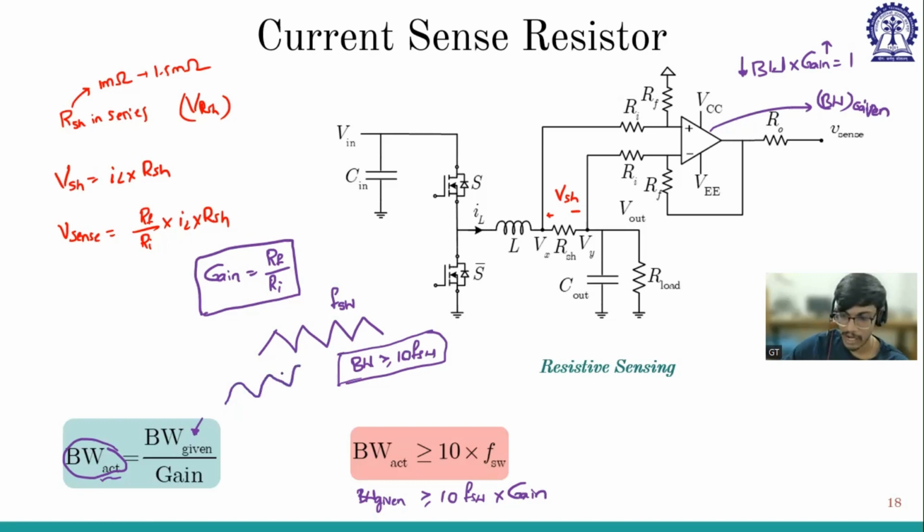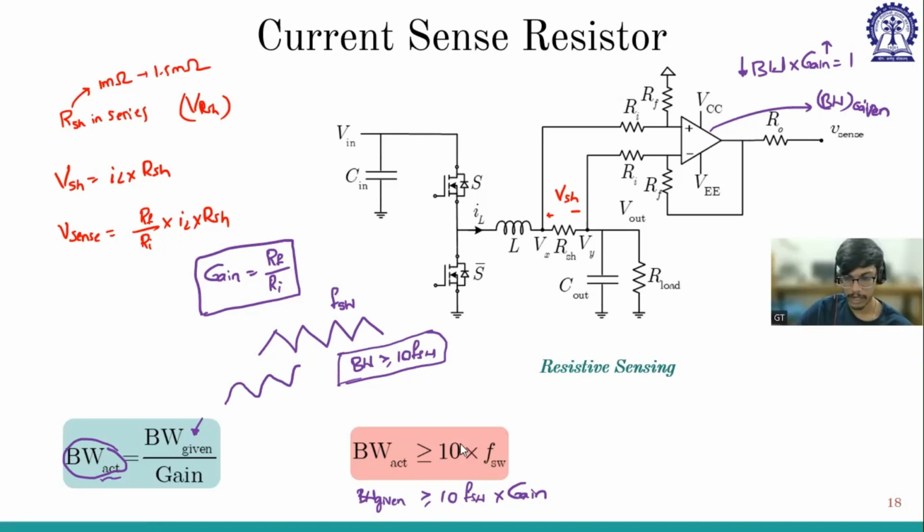So it is like filtering out, right? The higher order frequency components might be filtered out, and offset with low frequency components will be present. So we will not get the exact peak. If you want that peak, which we actually want, we should keep this in mind and take the op-amp which will hold this.